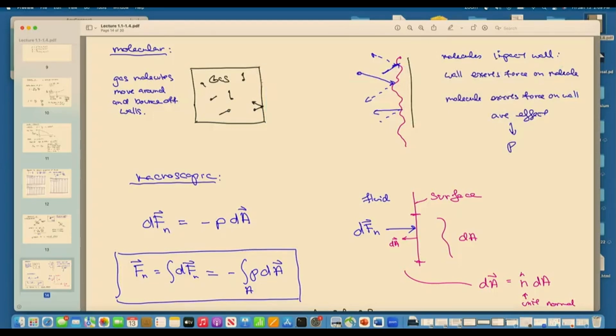So knowing a pressure distribution along this surface that is submerged in the fluid, we can evaluate the force due to the fluid on that surface through this equation here. And this would be the same also for example, that little sketch that I started off with today of an airfoil. Flow over the airfoil will set up a pressure distribution over the airfoil.